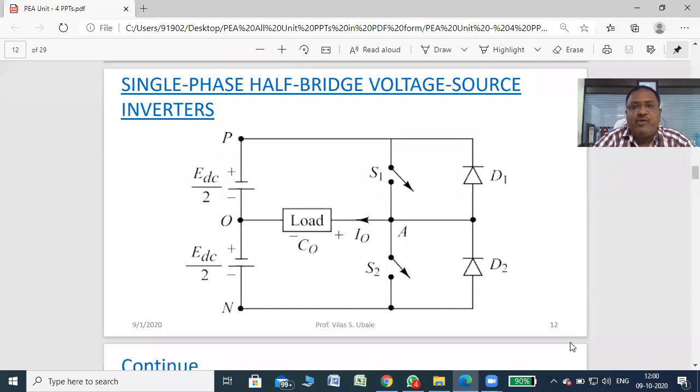But keep in mind, if we are using power devices, it means that definitely there will be a circuit required to drive the device, that is a gate drive or base drive. In case of a power transistor, we require a base drive. In case of power MOSFET, IGBT, GTO, SCR, we require a gate drive circuit. The gate drive circuit may be a UJT triggering circuit or a microprocessor based triggering circuit or any other triggering circuit.